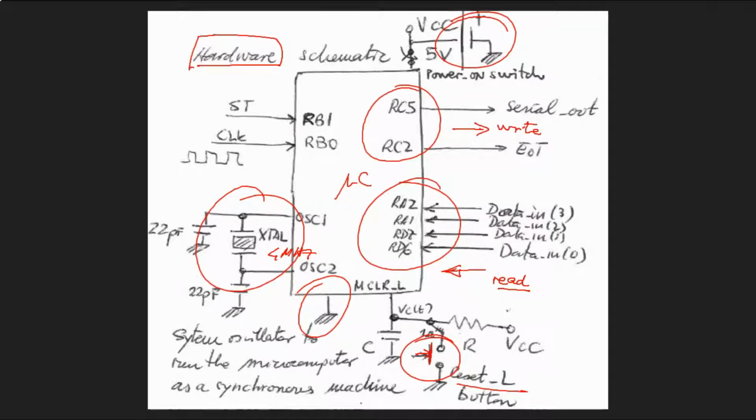All right, that is the typical and usual way. But here in this application, we have to detect, for example, the rising edge from the start button. When you click the start button, you generate the pulse, and you have to detect that so that the transmission sequence can start. And later, after you have detected this start button, what goes next is detecting precisely every single rising edge of the clock, so you can transmit one bit at a time.